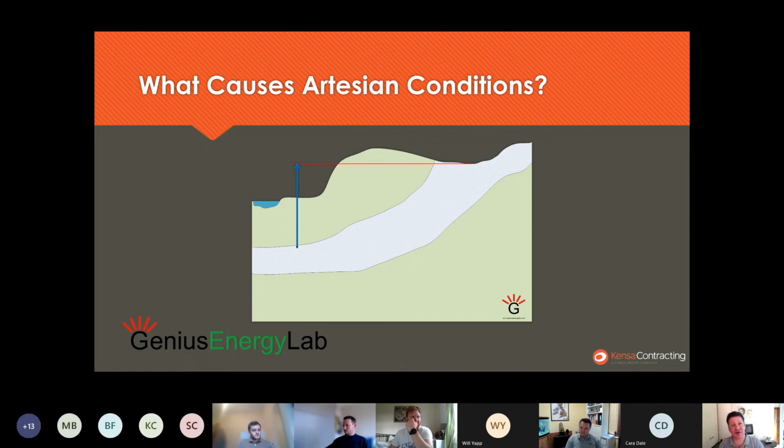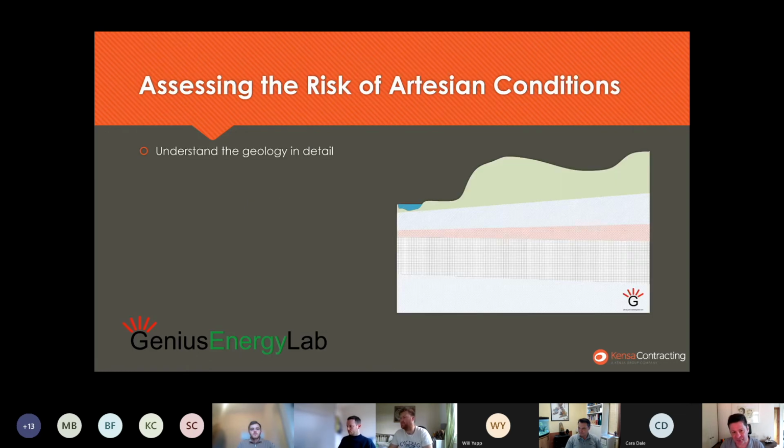You tend not to have the problem. So in the Thames sequence, where the chalk tends to be, you might have a problem with arisings, but you generally don't have problems with Artesian conditions, no. So I'm going on to how we investigate it in a second, and maybe it's a bit relevant to one of my slides just in a minute. So I'll come back to that if that's okay, Duncan.